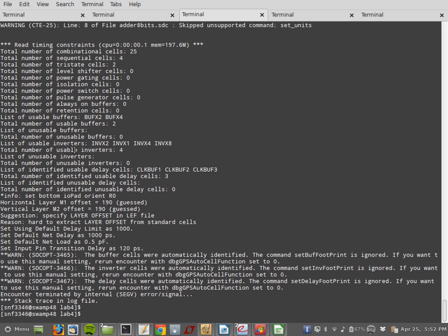I just wanted to show you the layout and how you can get the area, because from the layout you get an exact area of your circuit. So that's the whole point. Also, you can take that layout and put it into Cadence and simulate it in Spice using all the parasitics that you get from the layout, but we're not going to go over that because it's complicated.